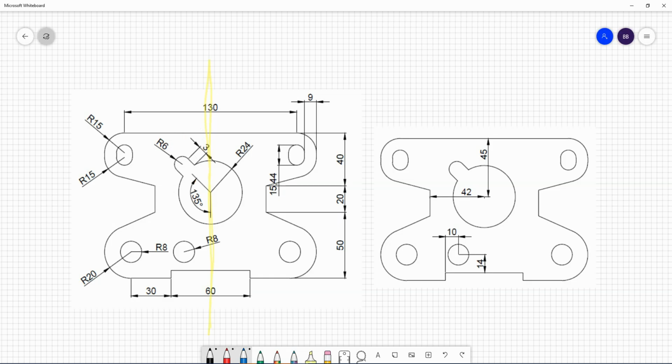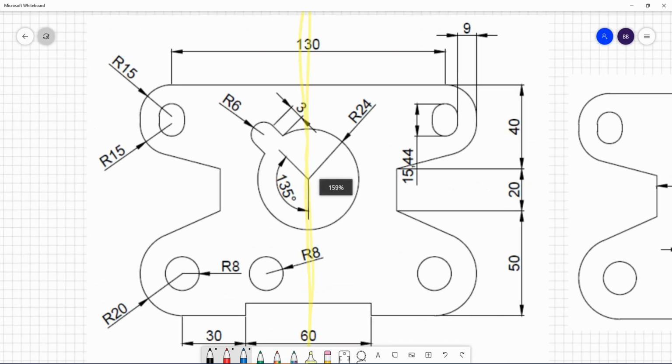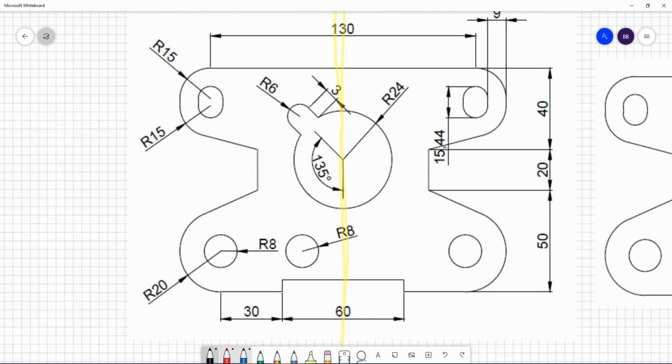So let's start by realistically breaking this down into nice sizable chunks so it's not a big scary drawing. So I'm going to first off put a construction line which will give me these two set points which I've marked in blue. From that I can create a series of offset lines for my construction which can allow me then to put in fillet points such as here and up here. This will allow me to set the dimensions and also allow me to draw in these features.